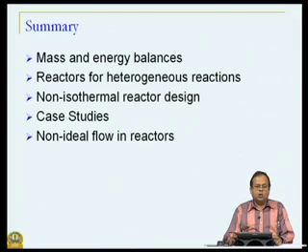We also saw that these age distributions or macro mixing alone does not determine the performance, because for the same distribution you can get two different kinds of performances depending upon whether the reactor fluid elements, or the material inside the reactor, either interact with each other or completely mix, or remain segregated or separated from each other.